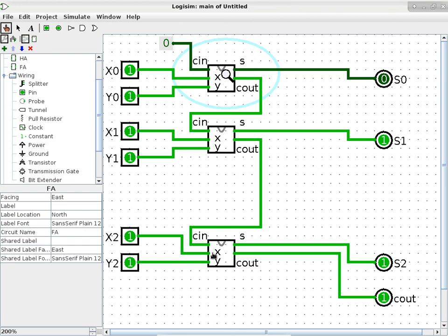over something that is determined by the width of the integers that you're dealing with? Because for this one, the actual time for the calculation is based on how many bits you have in an integer. If you have twice the number of bits, it will take twice as long. But the other design is almost constant time. Regardless of the number of bits in an integer, it still takes the same amount of time to calculate.